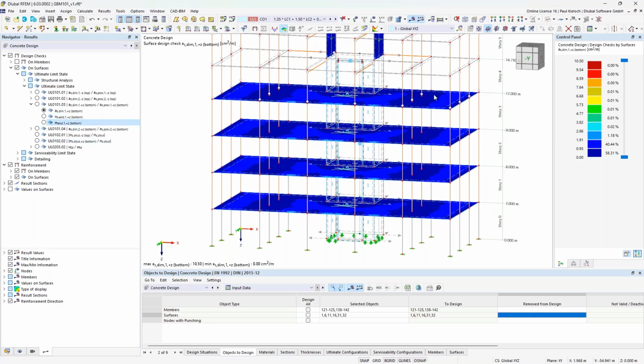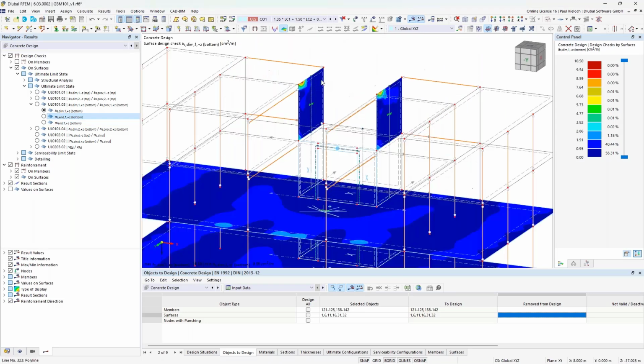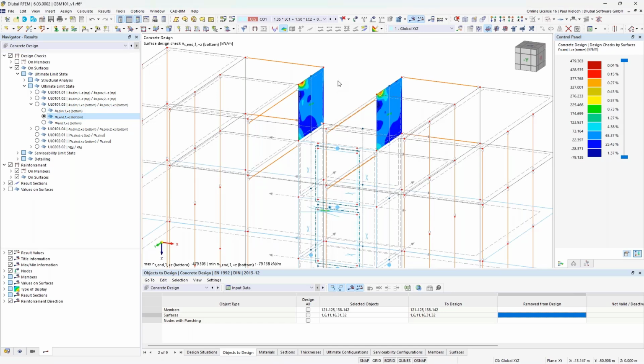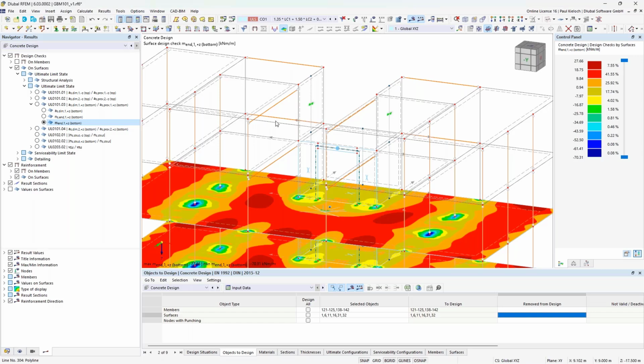So we now have, inside a 3D object or 3D structure, a separation between design membrane forces and design moments. For these regular walls on this end, that's why I've randomly selected these two slabs here, we have these regular design membrane forces. So it's like you would design regular 3D objects. And this new setting here in the context of a 3D file is the design moment.